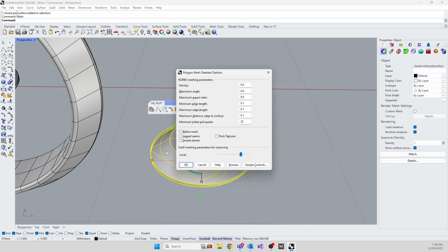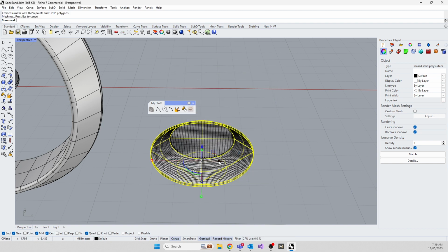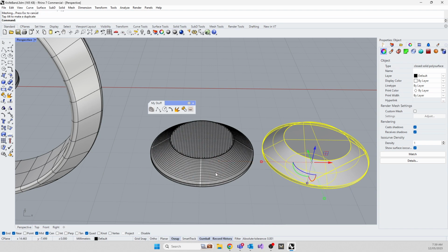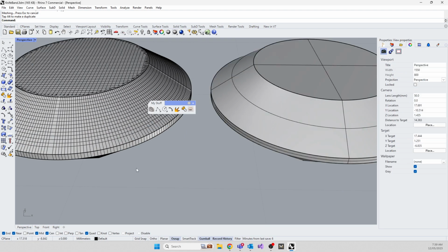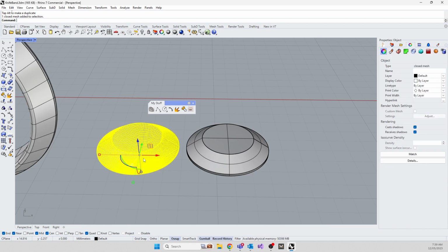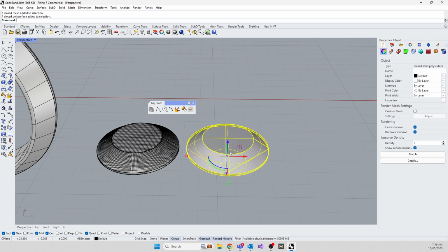So let's go mesh. I use a very tight mesh for when I'm doing 3D printing, and I'll show you what that looks like. So that's a lovely tight mesh. And it's mostly already got quads in it, and the quality of what I'm going to print versus what I see is identical. So now, let's leave that one over there and show you the bad mesh.